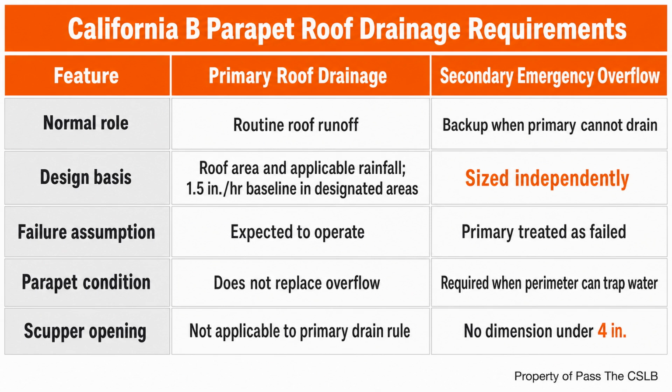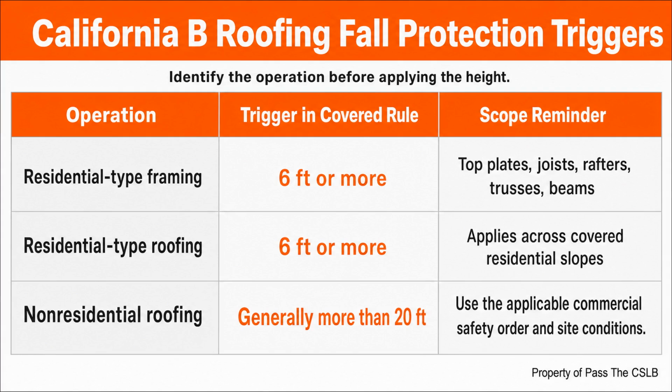Non-residential roofing is covered differently. The supplied material identifies a general trigger of more than 20 feet for the commercial roofing operations described there, subject to the applicable safety order, work method, equipment, and site conditions. I do not use that commercial threshold for residential framing or residential roofing.